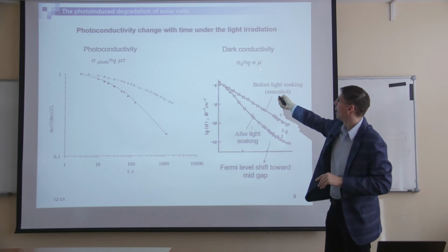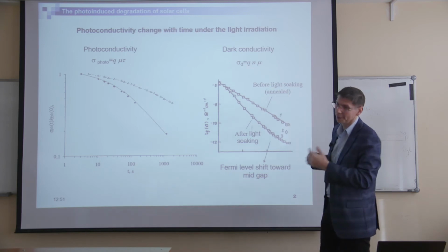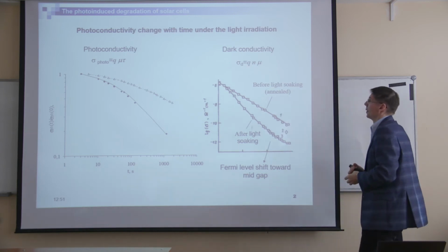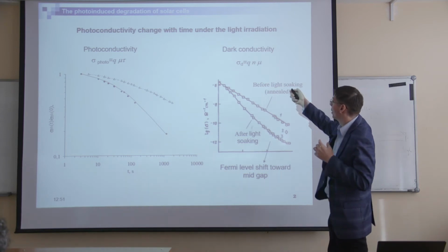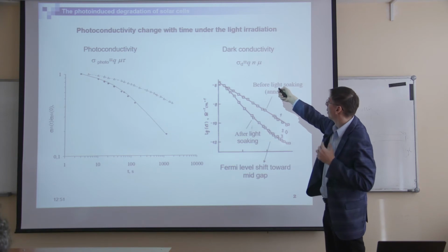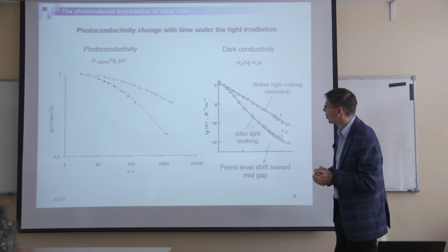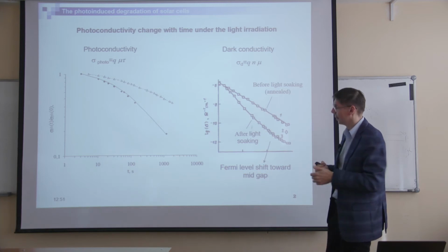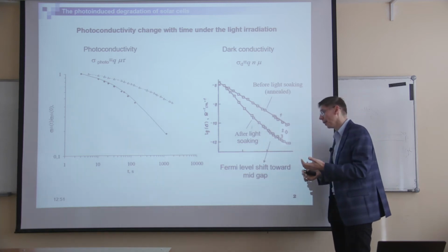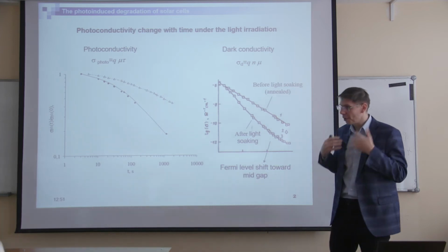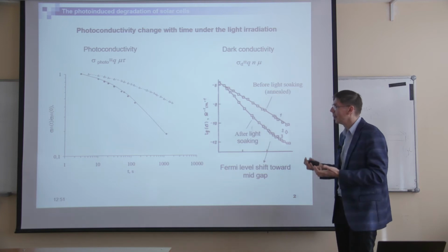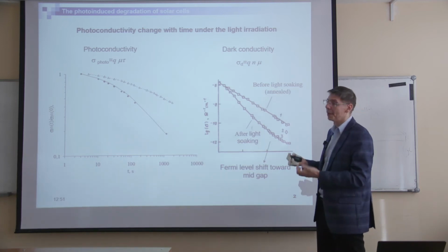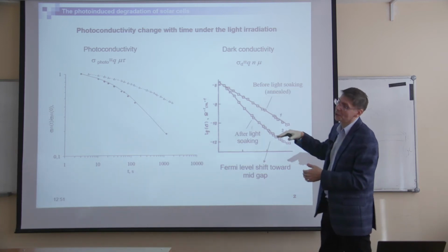So any conductivity could be expressed by this expression, but concerning the amorphous silicon, the concentration of the charge carriers actually depends exponentially on temperature. It is also related to the high defect density of states, which fix the position of the Fermi level.